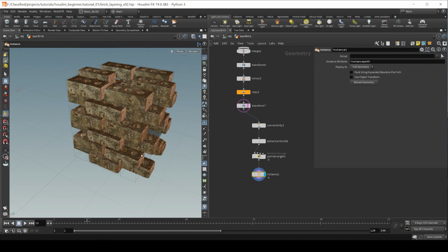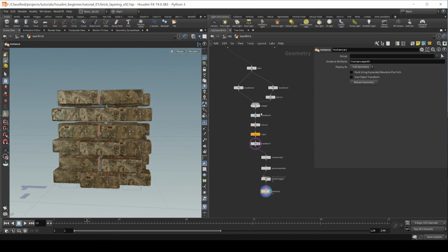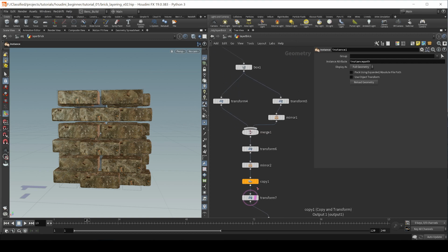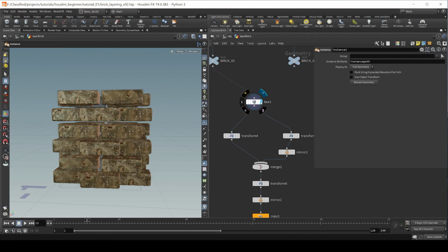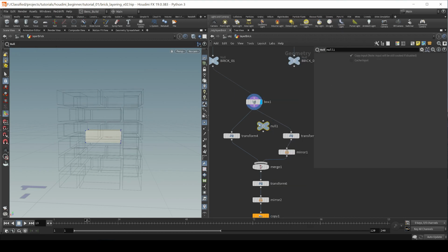However, the orientation is not correct because Houdini needs a set of vectors or an attribute in order to give it a proper orientation. And there's an easy way that we can do that. And this is what I wanted to show you beforehand up here. Before we do any of these transforms, let's go back up here to our box. And I'm going to drop down a null just to encapsulate this so it feeds down to all these others.